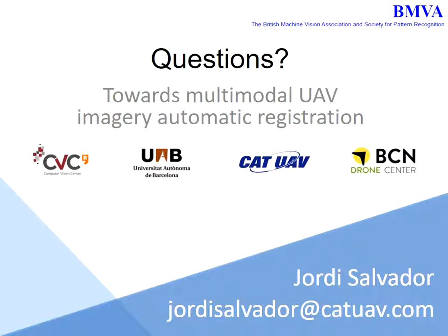No. Okay, the error is evaluated from the ground control points we made. What we do is generate manual control points that we know are exactly the same position. With that, we get a transformation that will directly fit those points to the orthophoto. And with that, we can evaluate afterwards how these points are reprojected from the final result to that one. But that depends only on the height difference that you have in the terrain. If you have 1 meter height difference at the corner, you have probably 1 meter shift in the position. So if you're not considering the height situation, how can you estimate the error?